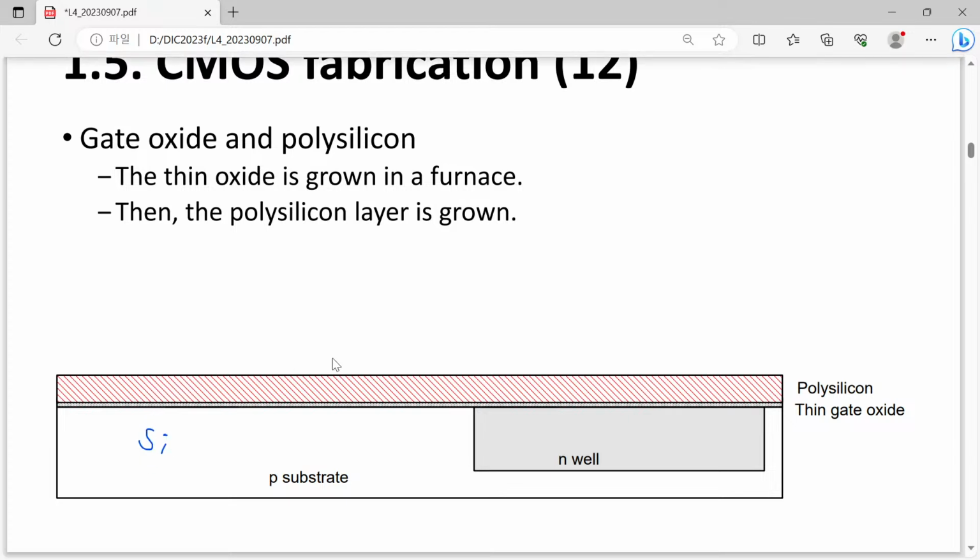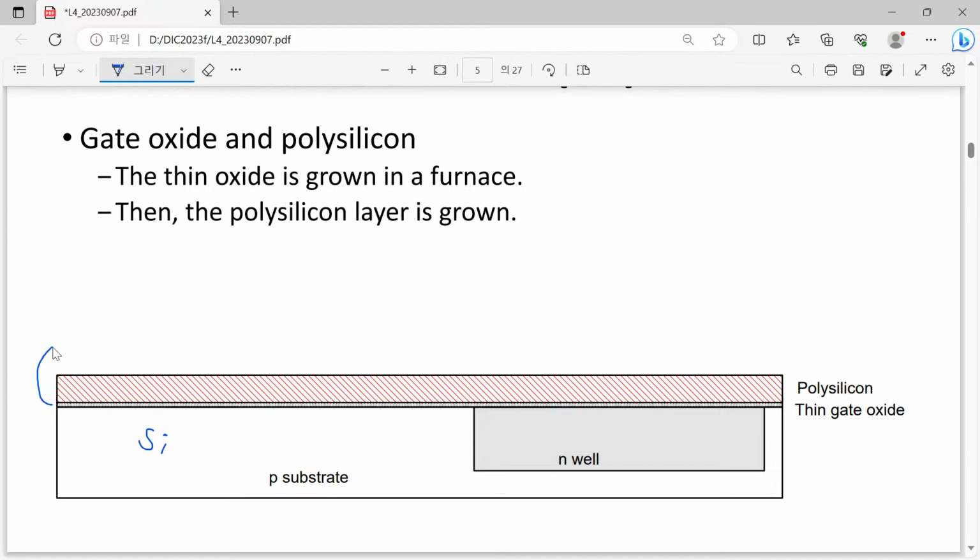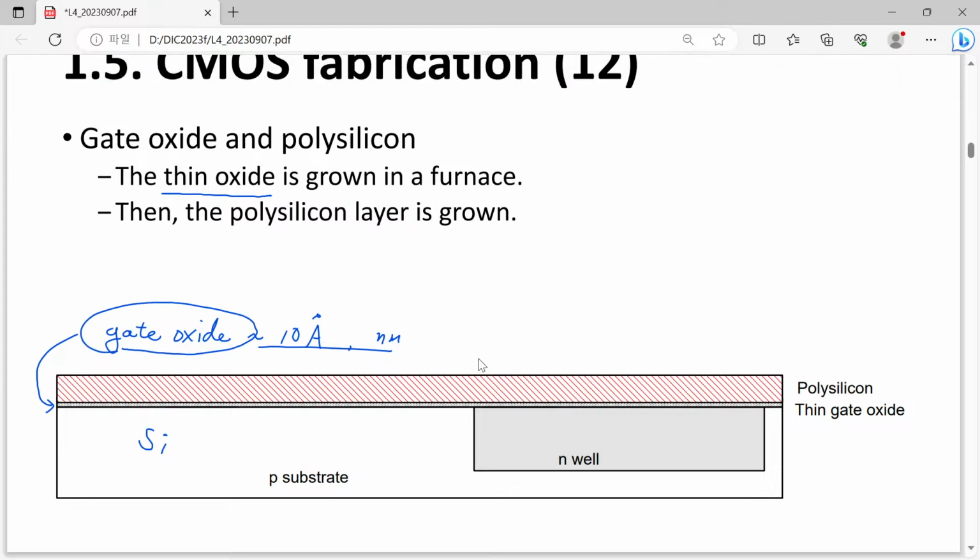This is crystalline silicon. However, a MOS system always needs very good quality gate oxide. So now we introduce a thin oxide, and its thickness is just a few tens of angstroms, on the order of nanometer scale. However, I have to emphasize that this pure silicon gate oxide applies to somewhat old technologies, and nowadays in reality the thin oxide is no longer just a thin oxide.